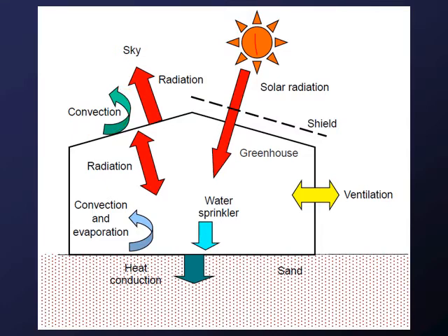It's actually convecting heat off the surface and removing it with the cold air as it touches it. Another thing to keep in mind is irrigation. So when you sprinkle a crop, whether it's overhead or whatever, that cool water cools the air, not only through evaporation, but just from the fact that oftentimes the water is a cooler temperature. So a lot of things going on in a greenhouse in terms of heat being stored, radiated, and absorbed.